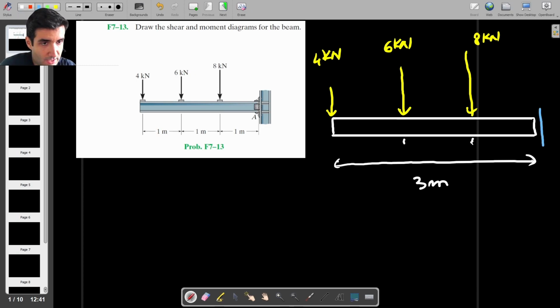And then, of course, I'll use my normal convention of putting the shear force down on the right-hand side. And then we have the bending moment, which is like this. The reaction, I should put like MR and also SR. Okay, so in this case, we have 3 point loads, which means we'll have to do 3 sections. Because remember, point loads are discontinuities in both the shear force and the bending moment graphs.